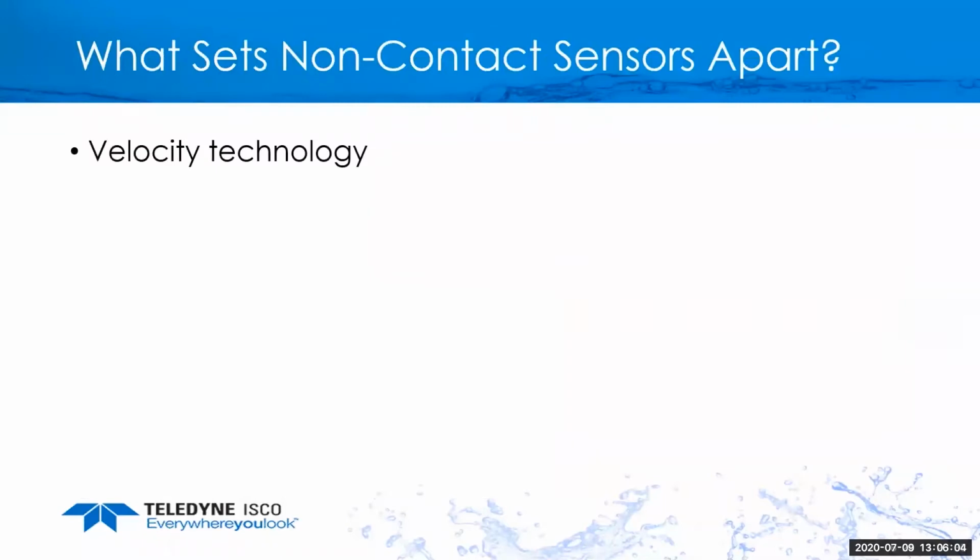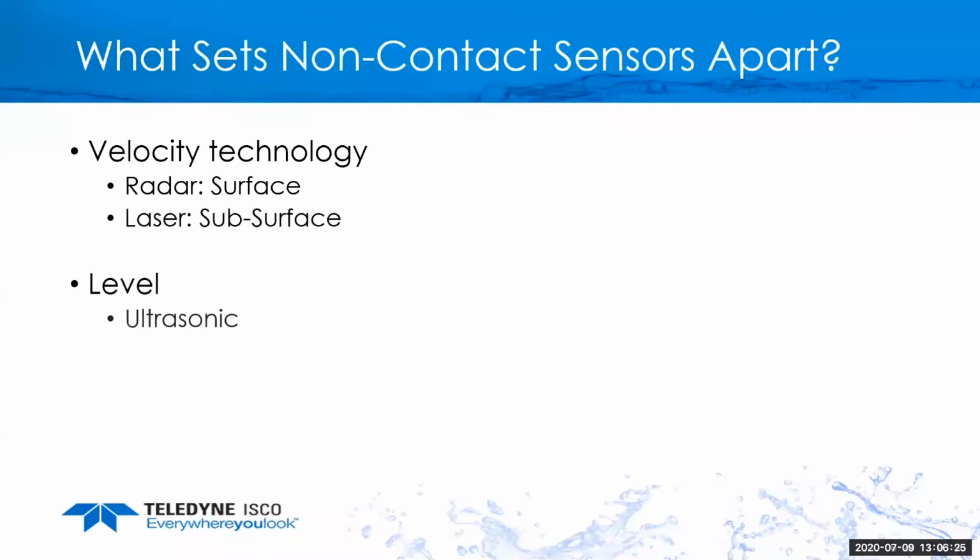So what else sets the non-contact sensors apart? Well, the velocity technology is the main thing. So radar sensors read the surface velocity to calculate the average velocity. The laser reads subsurface, below the surface of the water. And the level for both radar and laser use an ultrasonic sensor to read the level. And with the ultrasonic sensors, they can either have a built-in ultrasonic sensor or a remote ultrasonic sensor, depending on your application.